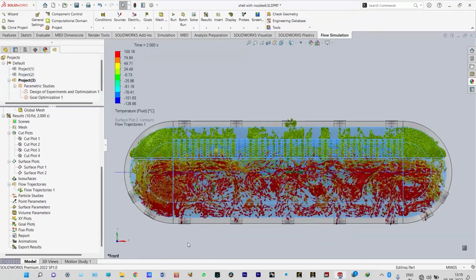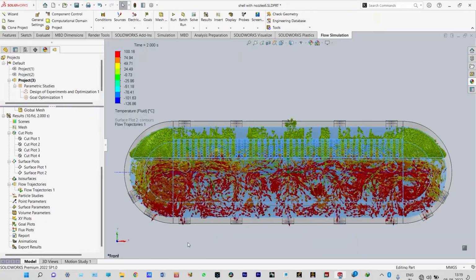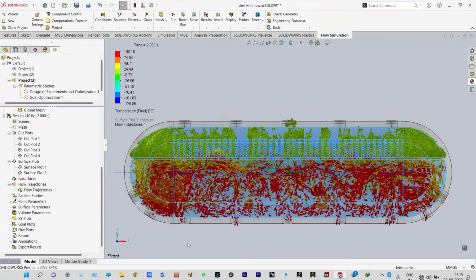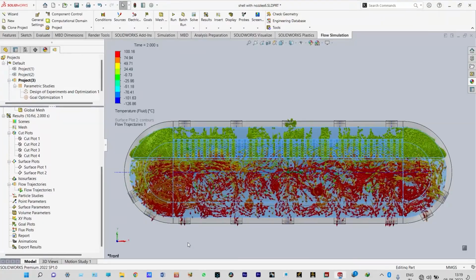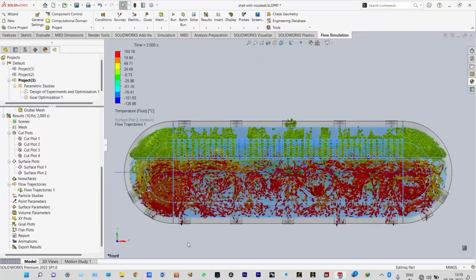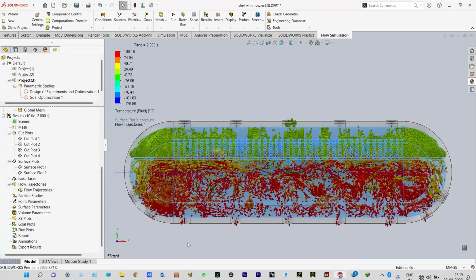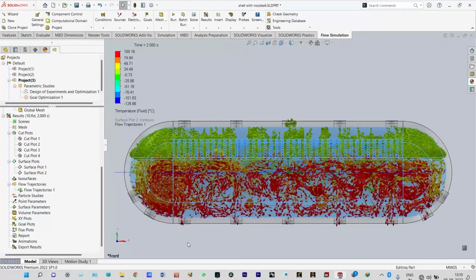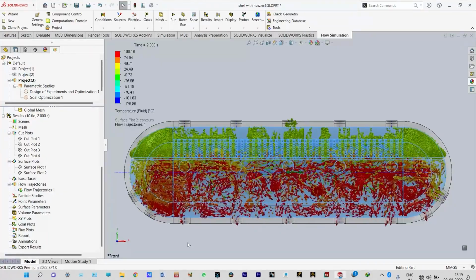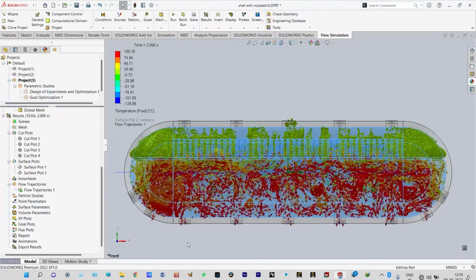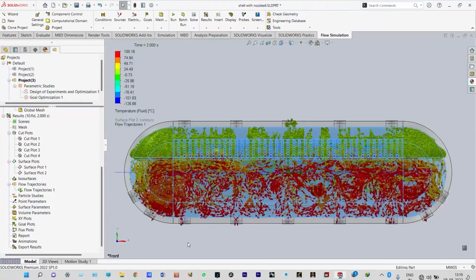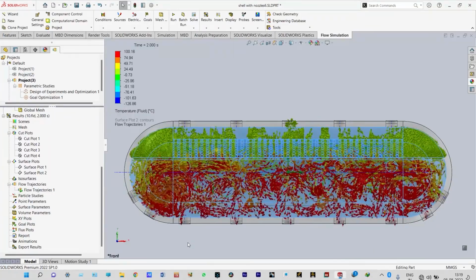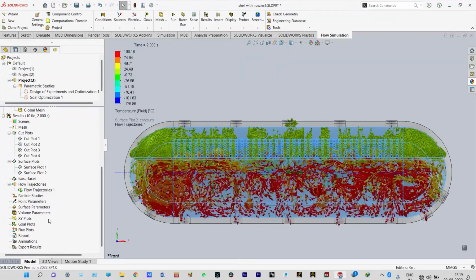So in this simulation, one very important thing can be viewed, that is the temperature at the top surface of water. It will not be reduced that much. Always it will have a temperature in the range of 100 degrees centigrade approximately, and at the exit level we can have a different temperature based on different input values of mass flow rate. That one we'll see during our parametric study, right? And we can have the desired level of temperature at the exit surface by optimization. That one also we will show in our analysis, right? Let us clear and hide this one.